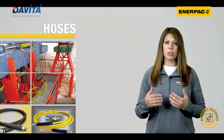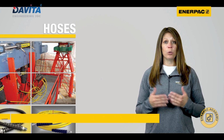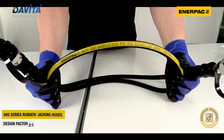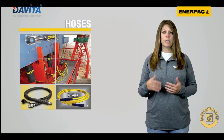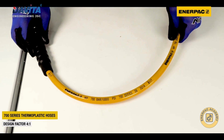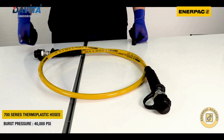Specifications for high-pressure industrial hydraulics consider these products to be used in static conditions and can safely operate with a design factor of 2:1. The ENERPAC 900 series rubber hoses, sometimes referred to as jacking hoses, meet the 2:1 safety factor. In certain regions around the globe, a 4:1 safety factor is required, even for high-pressure industrial hoses. In most of these regions, the ENERPAC 700 series thermoplastic hoses are used to meet these requirements, as these hoses have a 40,000 psi or 2,800 bar minimum burst pressure.